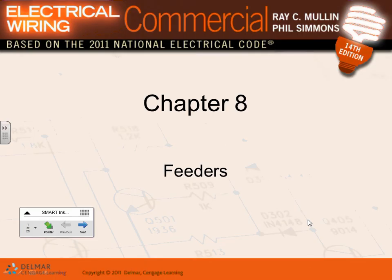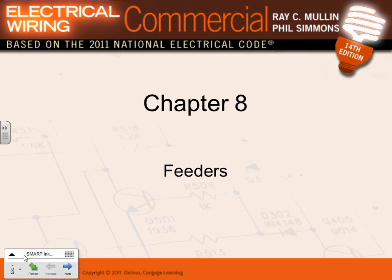Sizing feeders. Jeff, if you remember, our project was a 500 amp panel. We brought the service to it, and then we took a 100 amp feeder for the 100 amp panel receptacle, and we took a 225 amp feeder to feed the 225 amp panel. That's what this chapter is doing.